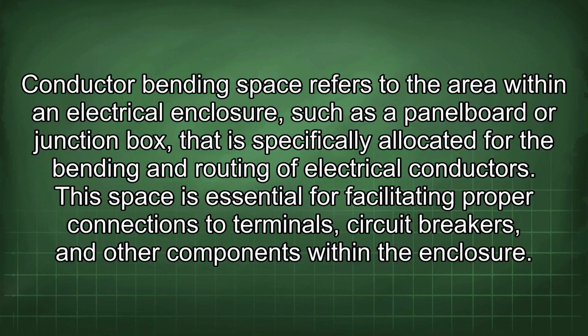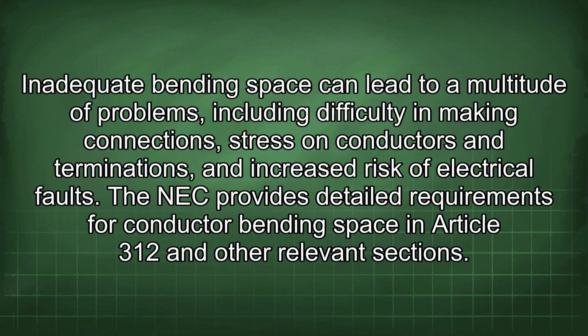This space is essential for facilitating proper connections to terminals, circuit breakers, and other components within the enclosure. Inadequate bending space can lead to a multitude of problems, including difficulty in making connections, stress on conductors and terminations, and increased risk of electrical faults. The NEC provides detailed requirements for conductor bending space in Article 312 and other relevant sections.